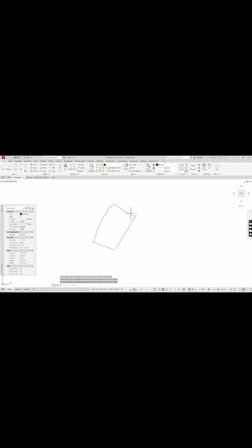Usually I import the boundary of the previous data. As you can see here, I've done my edits. I've imported the boundary of the previous data, and I'll be using that to ensure that the polygon or the polylines are closed. Make sure there are no gaps. Here I have 2 polylines. I'm zooming in to make sure it snaps properly, no gaps.